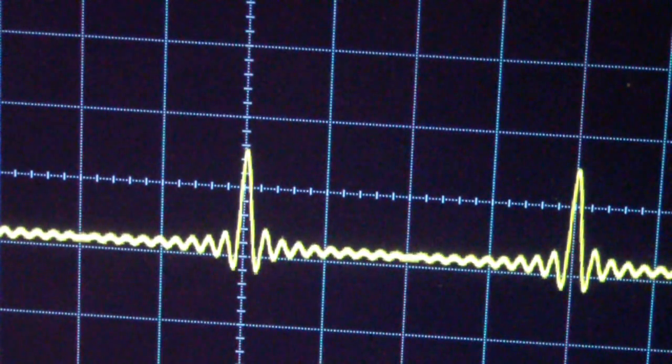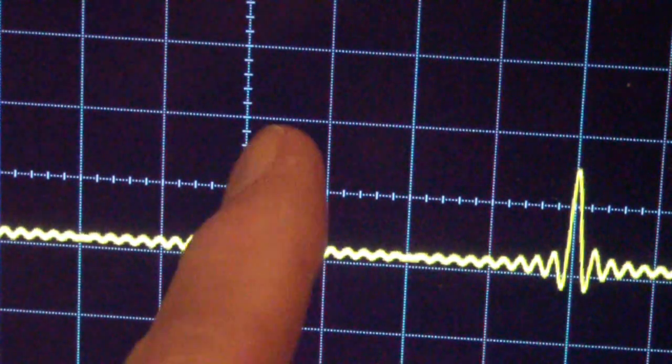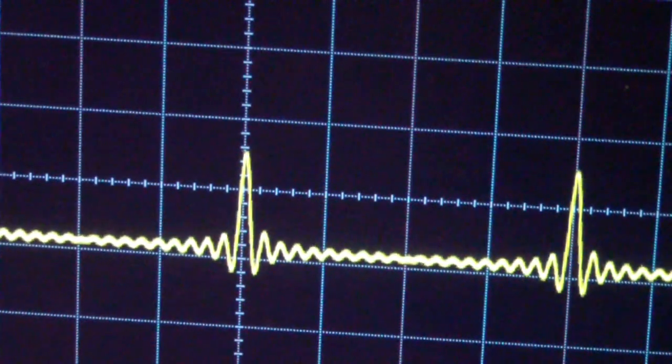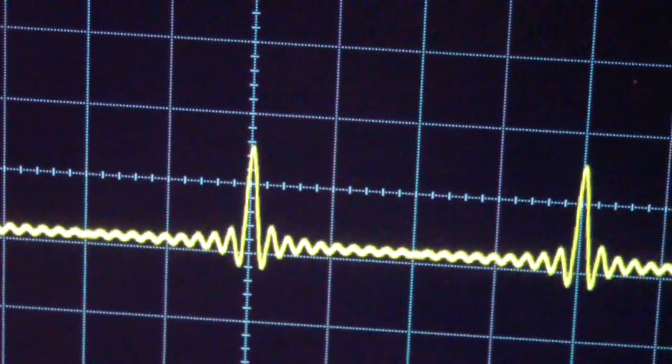Now, this is a useful mathematical term because it can be used to do analysis of transfer functions. And so some arbitrary waveform generators will generate a sinc pulse. Now in this case it's the same frequency. 1 megahertz is the basic frequency. In other words, there are 1 million of these pulses every second. So let's take a look at what it looks like on a spectrum analyzer.